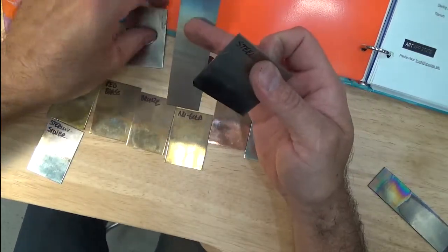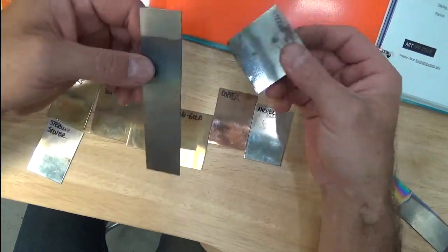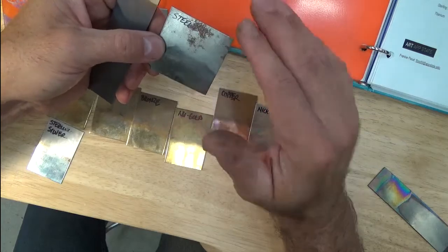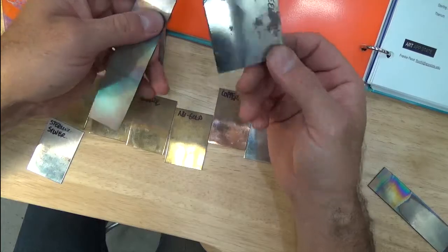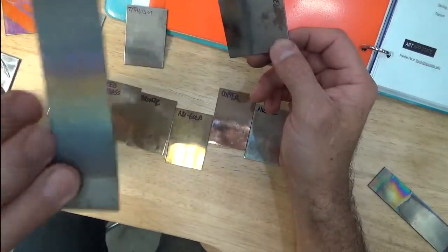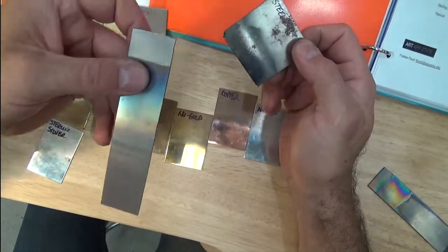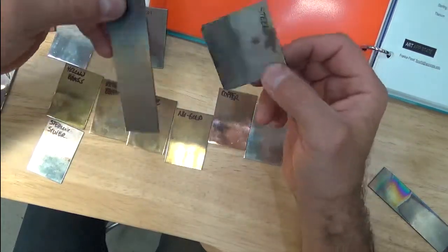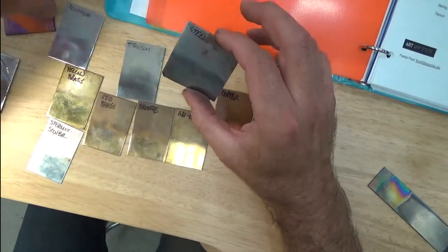And there are various handouts. I've got a few on this, but you can basically judge the material qualities, and steel comes in various alloys as well, but you can tell how high or how low the carbon content of steel is by the spark that it throws. And a similar thing in terms of recognizing titanium is that if you grind titanium, it also will throw a very, very bright spark. And so if you're interested, I can show this in class at some point when we're back in person, and I can show you the various.